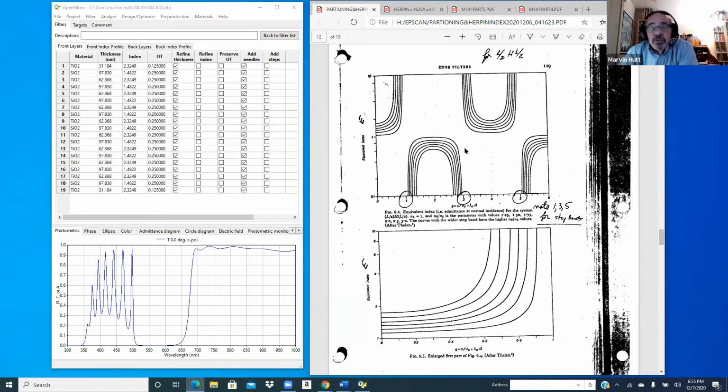optical coated material control is the name of the game, stoichiometry. And if you go into an optical coating house, you will see all the coating machines in the visible section have only 2 materials in them, SiO2 and TiO2. Why? We know these materials, they're hard, they're glassy, they don't produce problems, and they make very good glassy-like films.